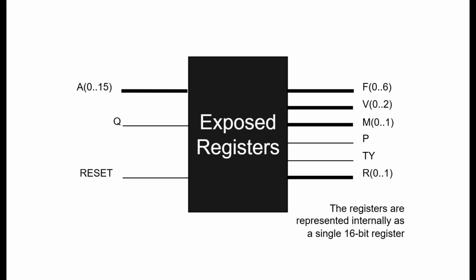There are 6 accessible registers that operate like this. 3 bits for video mode operation, 7 for the base address of the video memory, 1 bit for the memory page, 2 for CPU speed, 2 for memory size, and 1 last bit for the memory map type. A total of 16 bits of register and 32 bytes of address space.